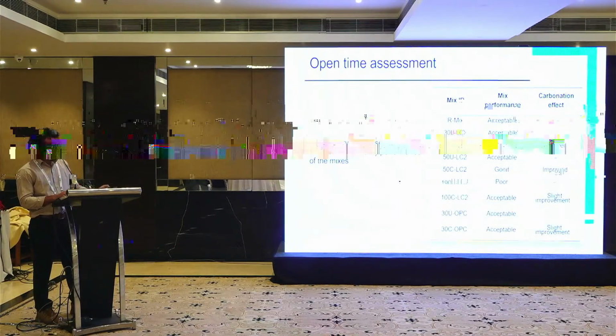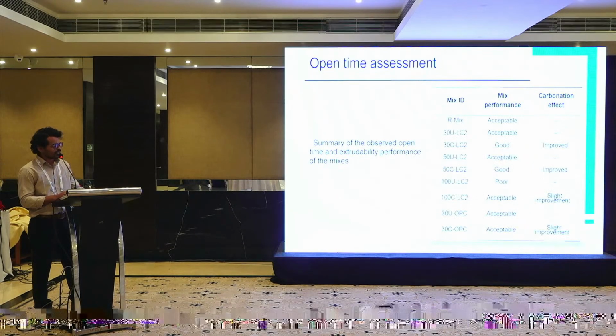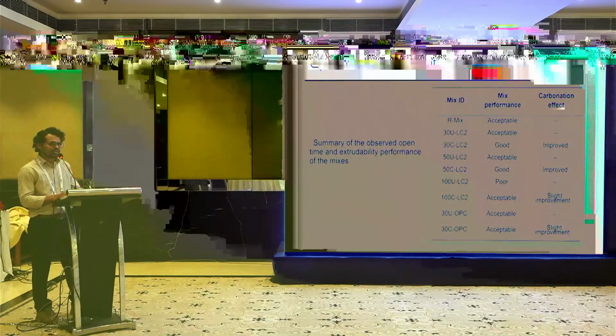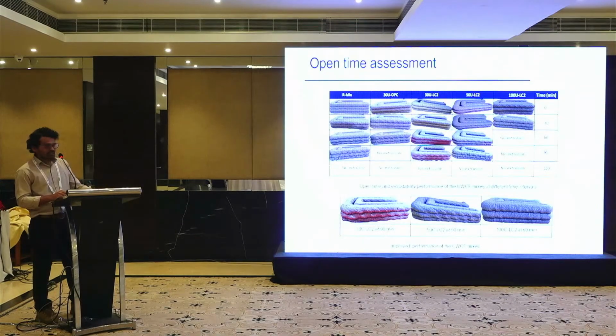In a similar way, the mixes performed well after carbonation, and after carbonation, some mixes even performed in the very good category. This is because the calcium hydroxide and calcium oxide form carbonate during the process, which reduces the water absorption by filling the pores present in the waste concrete fines. And here you can see the mixes with carbonation have a lower surface density index.